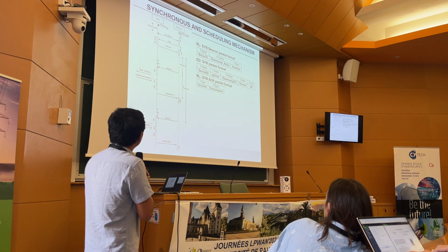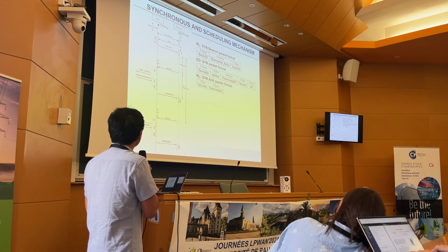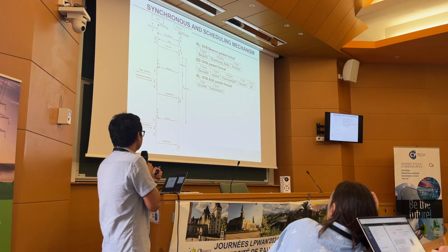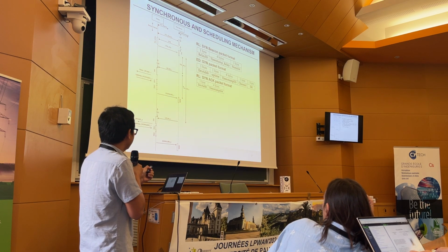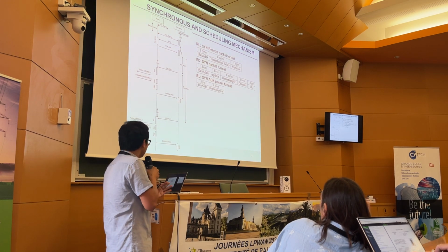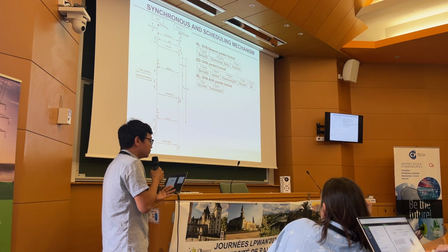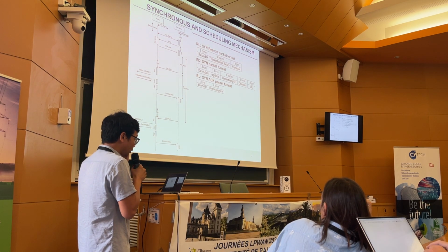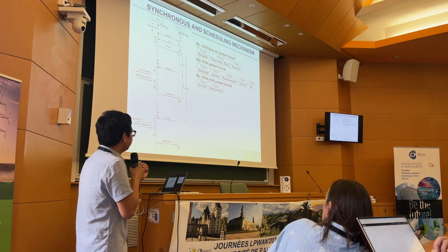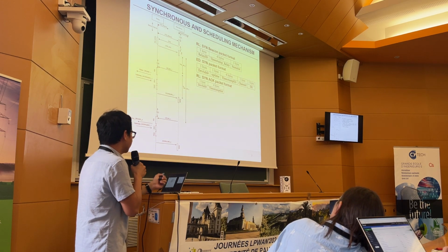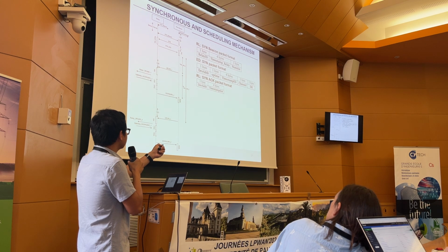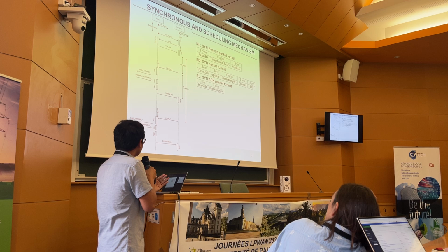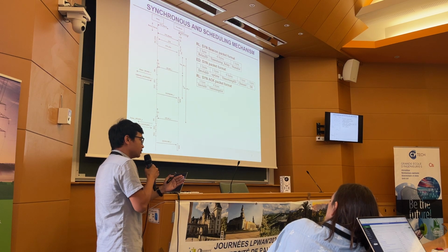Then the relay will send back the sync ACK in this format. It includes the device ID of the end device to confirm that the end device is available for this synchronous, and 4 bytes for the timestamp slot, which means the time for the next opening.